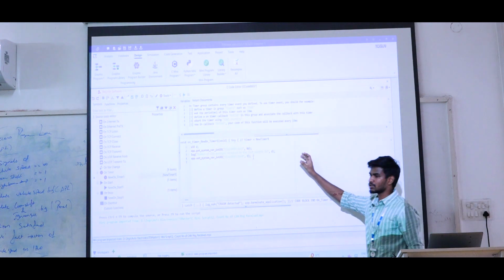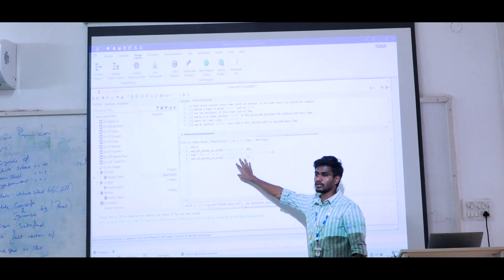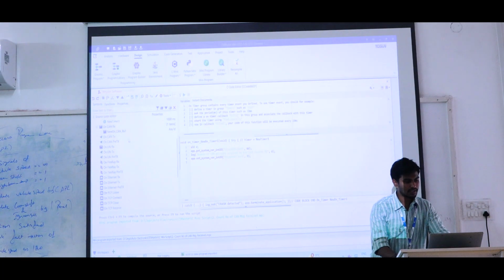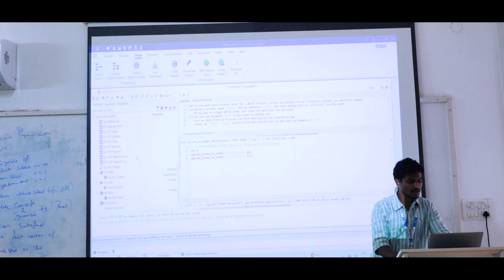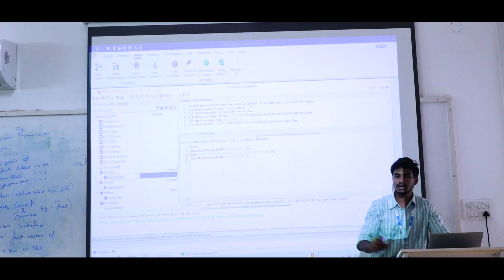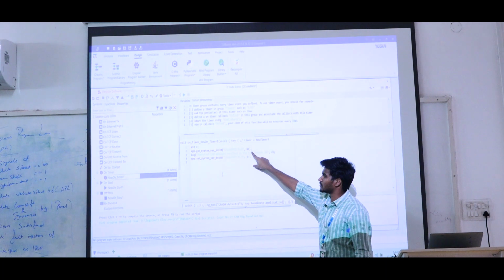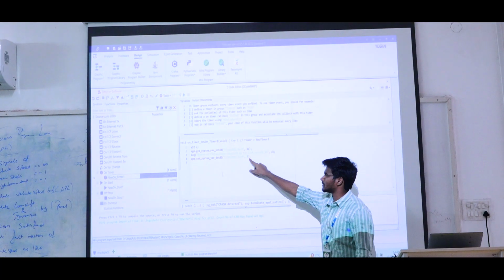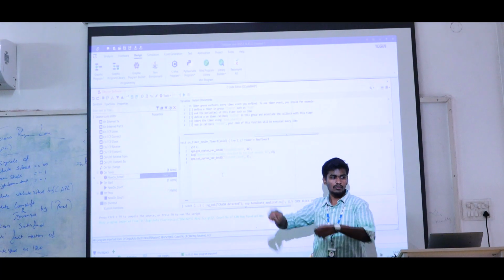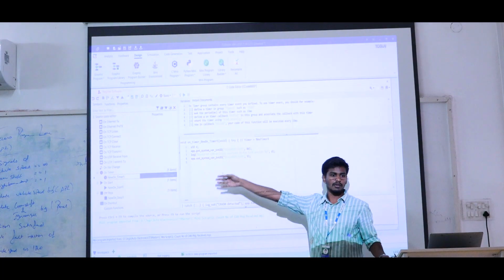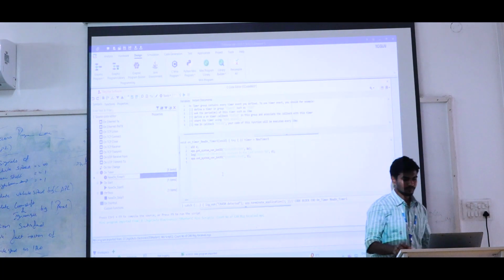The concept is that this code only prints the log value. In this RX we are just getting the messages, and with the log we print how many we received. After printing, we set the value to 0. So again, for 1 second, we count the messages received, because this code will work only after 1 second, as the timer is 1000 milliseconds.